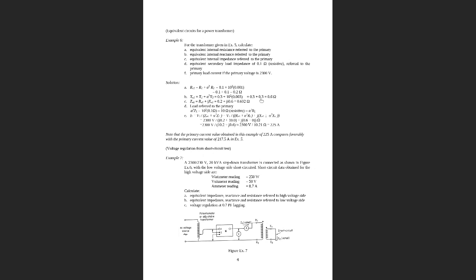So generally, why is it like this? Because I already explained to you in the previous one. The primary, high voltage, uses more turns. The secondary, low voltage, uses fewer turns. You know the reactance is proportional to inductance, and inductance is proportional to the turn number squared, right? And the voltage ratio is proportional to the turns ratio. That's why there is a square.